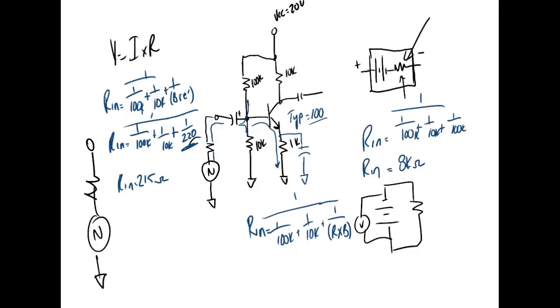Do you think the first amplifier we're going to run that antenna into is going to be bypassed? Well, no, that antenna's got at least 300-400 ohms worth of resistance in it, right? We usually have about a 300 ohm antenna out there. So it wouldn't even be able to drive the thing to get the gain, because it would drop all the voltage.